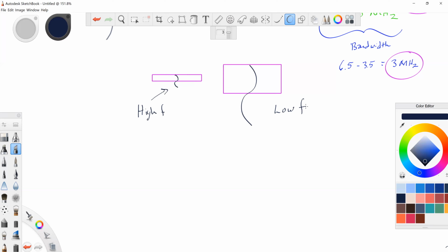Which properties of the piezoelectric element of a continuous wave transducer? The frequency of sound emitted by a continuous wave transducer is determined only by the frequency of the electrical signal that excites the piezoelectric crystal. Let me finish: the crystal's thickness and propagation speed do not affect the frequency of sound from a continuous wave transducer. I find that hard to believe, but basically what he is saying is, on a continuous wave transducer,